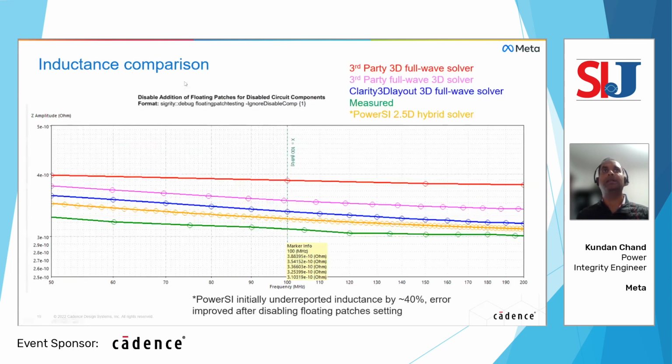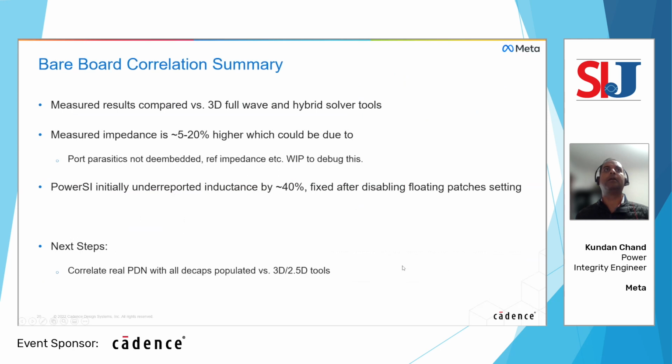And this is again the inductance extracted from the measurement for the board, just showing the results. Again, green is measured, and then you have the other field solvers' inductance numbers. So going towards a summary for this particular case, we intentionally created a short on the board to measure the inductance, and we were able to measure the impedance within 20% of all the industry tools.